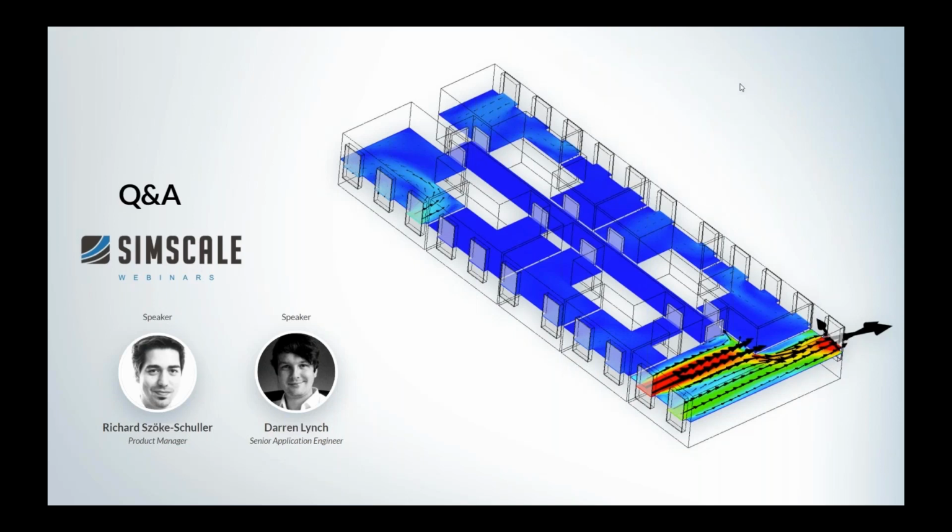Once again, Richard, anything to add to that? No, it was perfect. One thing maybe to add, you could also do, for example, a study on the outdoor analysis, for example, for 36 or 16 wind directions, and then put the pressure coefficient results into a different analysis software, for example building energy modeling tools, where you can then assess for the full year the typical behavior for each hour of the year in a faster way, maybe not as accurate as resolving fully the internal flow.